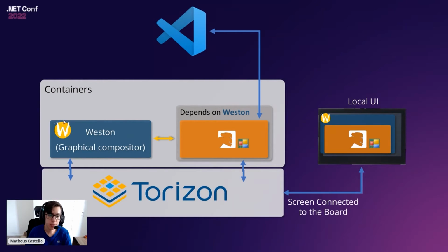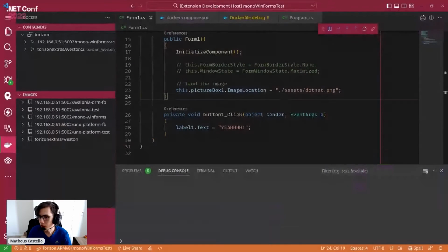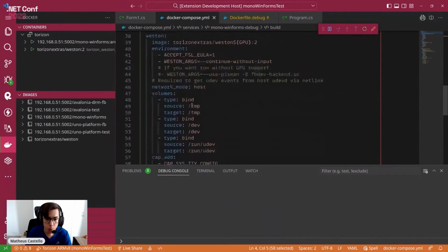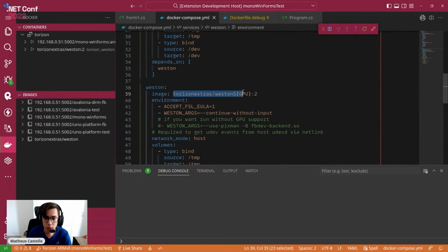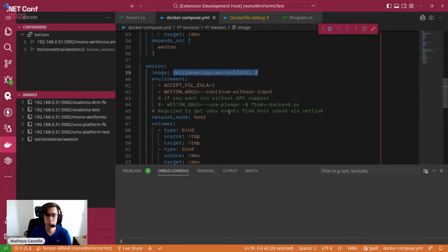For example, I can use the same Weston graphical compositor and change my application to one that uses X11 or Wayland, right? So you can also make a base with the graphical compositor and your application. And here, the graphical compositor comes from Toradex, from the developer of the operating system, so I don't need to build the Weston compositor myself. I'm using it here, right?